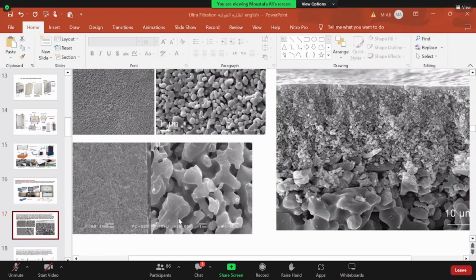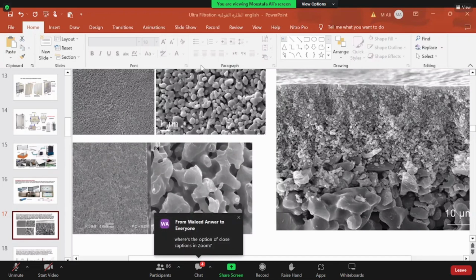normally has refractories inside of it to seal it and protect from the temperature, made from zirconia. Zirconia can take up to 1650 degrees Celsius, so it can tolerate the temperature of the incipient melting or fusion of the edges of the ceramic grains. Okay?